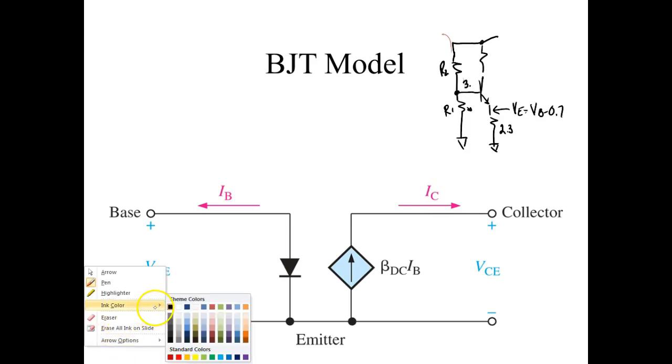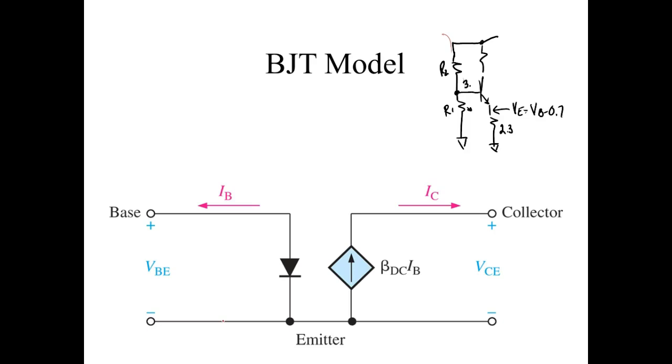So if I can calculate current, that's going to give me emitter current, but for all practical purposes, we're going to assume that emitter current and collector current are equal to each other. So if I can calculate that current flow, then I can calculate my collector current. I'm going to use IE and IC as being equal even though they're not, right? You understand that? If I know the size of that resistor and the current flow through it, I can calculate the voltage drop across that resistor. Then I can use Kirchhoff's law. If I know the voltage drop across this resistor and across that resistor, I can calculate voltage collector to emitter using Kirchhoff's law. I just subtract everything out, and that gives me the voltage drop across there. And I've solved for this transistor circuit.